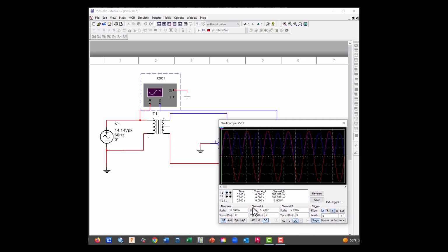Okay, so let's turn him off. But what you see here is we've got our positives. And what happened because of our diode setup, we've taken this alternation and we flipped it. So now we have a full wave, full voltage output. So let's turn him off and let's spread them out a smidge.